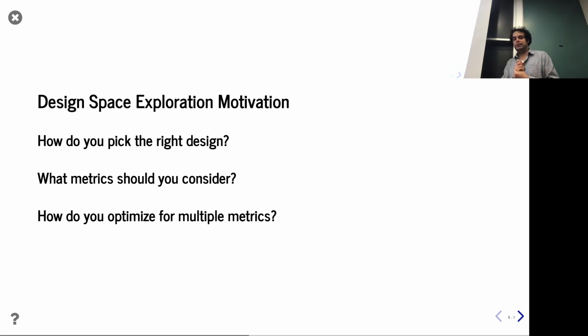And so naturally, you have to figure out what your metrics are. Given a certain problem, a certain goal I'm trying to achieve, how am I going to compare different designs? I need some sort of metrics to evaluate them. And it becomes very apparent with these hardware designs that usually it's not just one metric, there are multiple metrics subject to certain constraints, some hard constraints, some soft constraints, et cetera. And that's where DSE gets interesting: even if you have multiple metrics and you highlight what you care about, there are still going to be trade-offs, right?